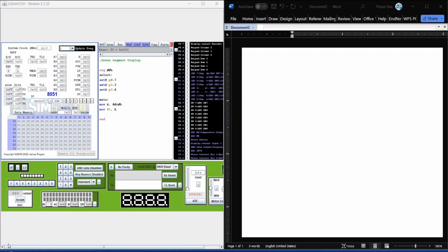We were trying to switch between the segments of the multiplexed 7 segment display, and we ran through some code which is also on our screen here. For this particular code, we know that it's going to display on the first segment. Based on the combination we did in class, the combination for A0 and A1 can now switch between the several segments.